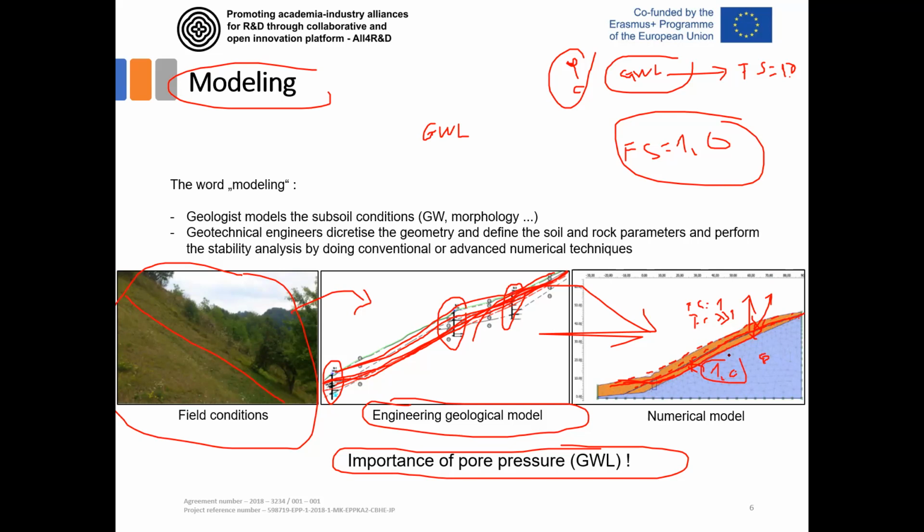That's why this groundwater level is usually at 1/2 or 1/3 of the landslide height, let's say the vertically measured depth of the landslide. So the groundwater should be at the middle of the landslide depth or even at the lower third part of this level, if we are not sure and if we don't have information on the groundwater level at the moment of sliding.